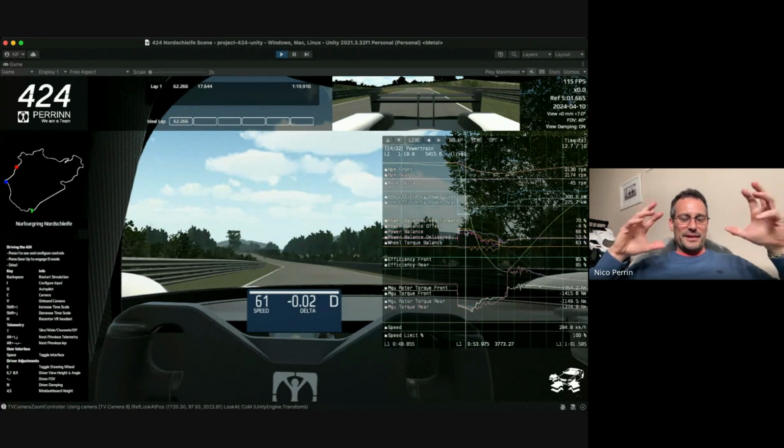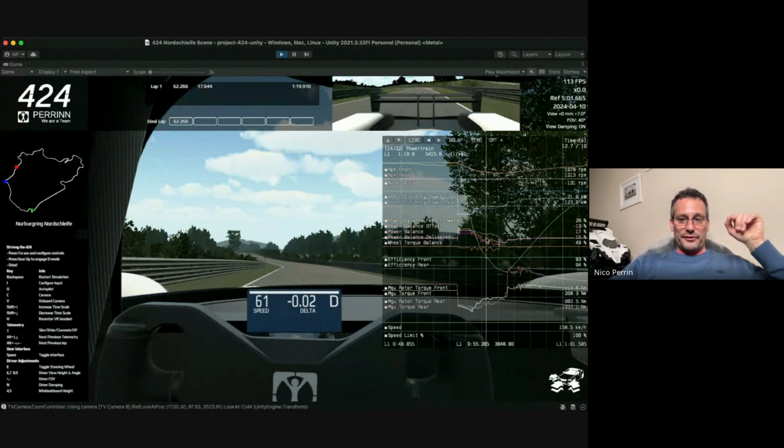And we do it on exit as well. So it's a bit like a traction control anti-lock system. It works relatively well, but it will not prevent the big events of locking. It's just a little help. As we release the brakes and we turn, the power balance goes to the rear. You can see now we're at 15%.